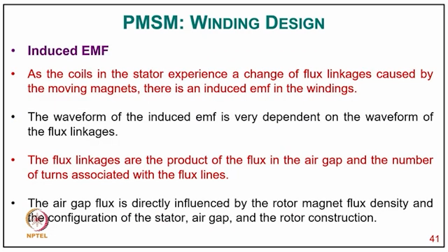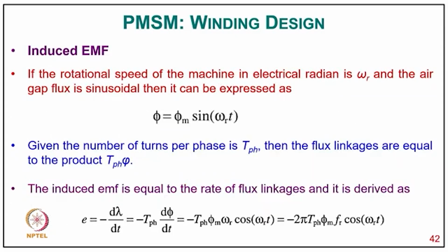Coming now to induced EMF. As the coils in the stator experience a change in the flux linkage caused by the moving magnets, there is an induced EMF in the winding, and the waveform of the induced EMF is very dependent on the waveform of the flux linkage. The flux linkage is the product of the flux in the air gap and the number of turns associated with the flux line. And the air gap flux is directly influenced by the rotor magnet flux density and the configuration of the stator, air gap and the rotor construction.